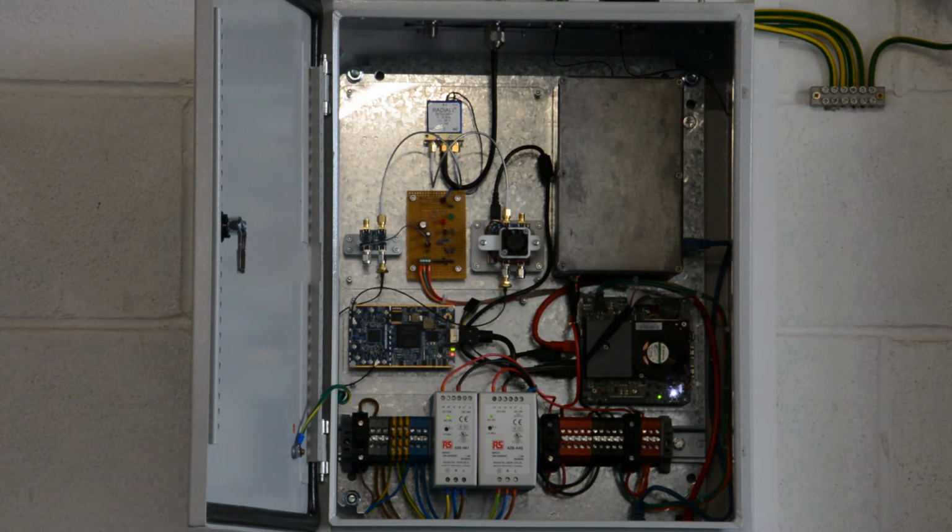So what we're looking at here is a wall-mounted cabinet that's got a remote radio head built into it, comprising of a LimeSDR together with an Intel Core i5 NUC. The LimeSDR is connected to a PA module and an LNA module. They are in turn connected to a coaxial relay, and then that's finally connected to a wideband roof-mounted antenna which covers 25 MHz to 3 GHz.